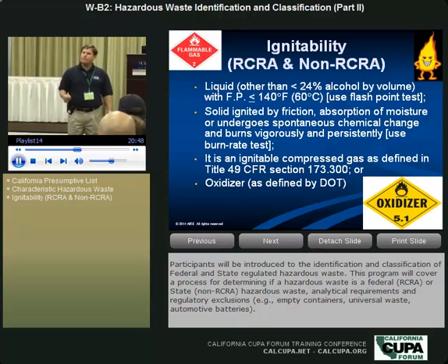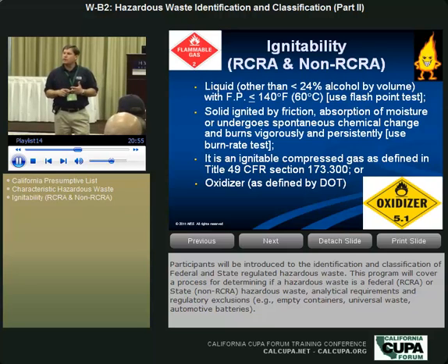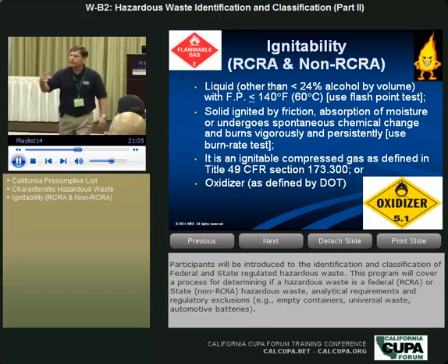Okay, ready? 1 atmosphere, 78 degrees Fahrenheit. Take a 5 cc representative sample of the waste, put it in a 70 micron mesh paint filter conical shaped funnel, wait 5 minutes, 1 atmosphere, 78 degrees, does it drip? Yeah, that's a liquid. What's in the filter is a solid. And your waste is a sludge, maybe both. But to check for flash point, it's got to be liquid. Because flash point is dependent upon the liquid.